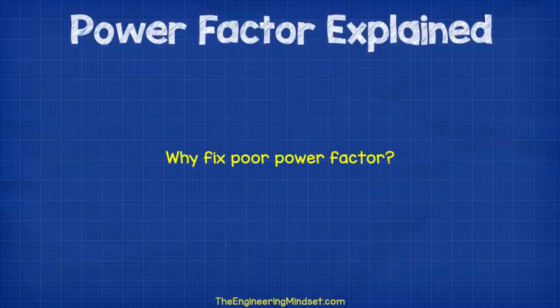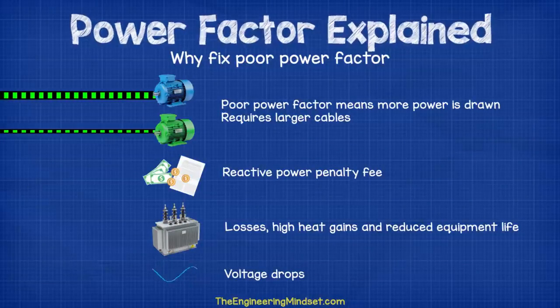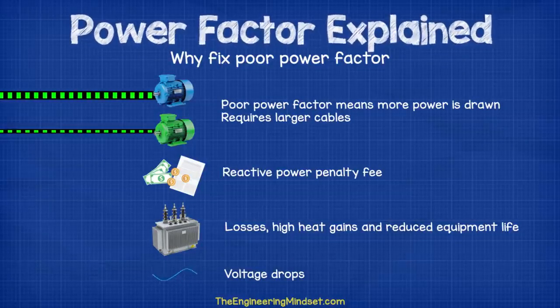So why should we fix poor power factor? Poor power factor means you need to draw more power from the electricity network to do the same amount of work. Therefore, the cables need to be larger, so the installation is going to cost more money.